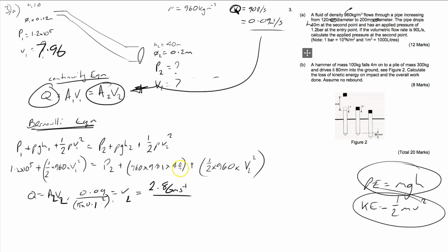Quick logic check: if we open up the aperture from the input, then it will have a drop in speed, which it does. So that's sensible. And they look like sensible values as well, not going through it like Mach 4 or whatever, which is good. Okay, so that's how we use the continuity equation to deal with missing values.